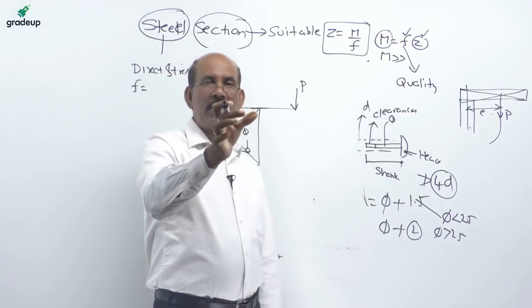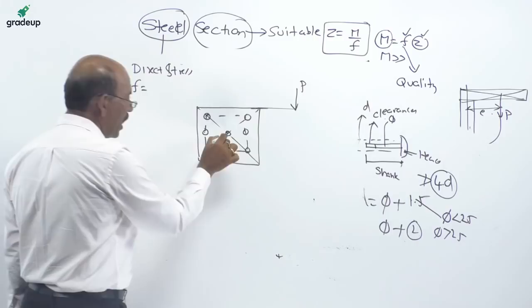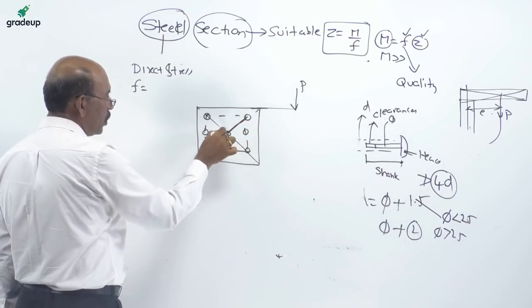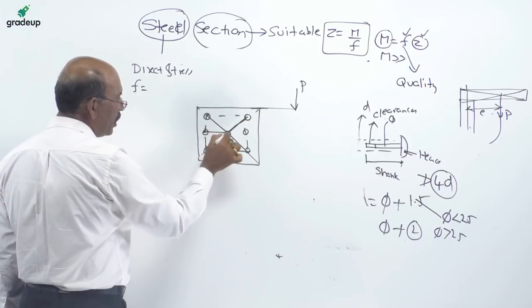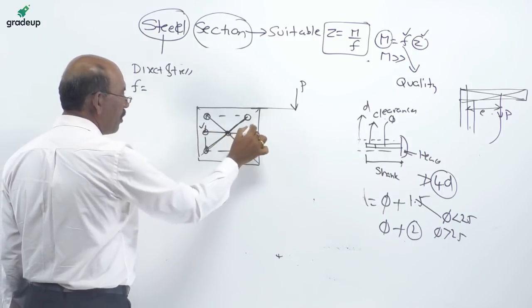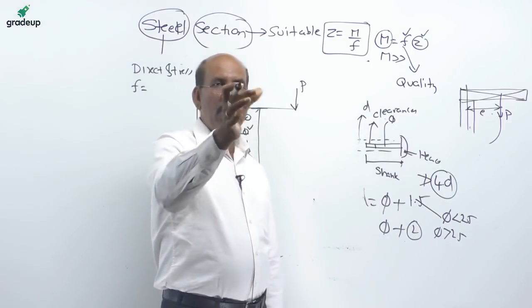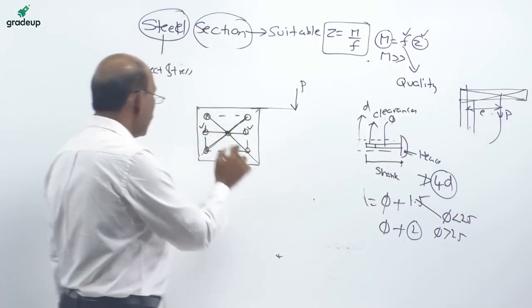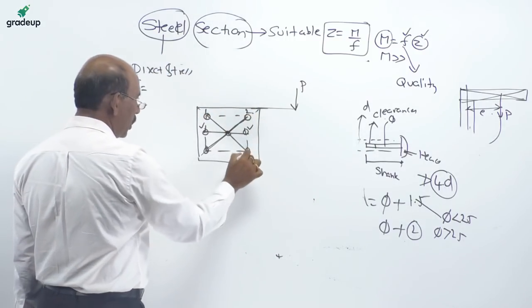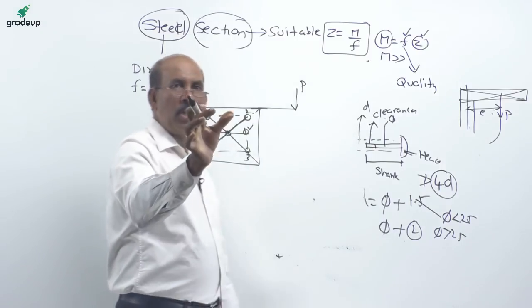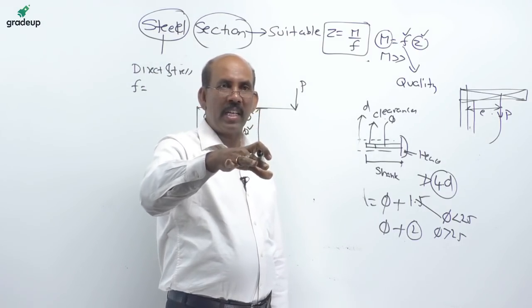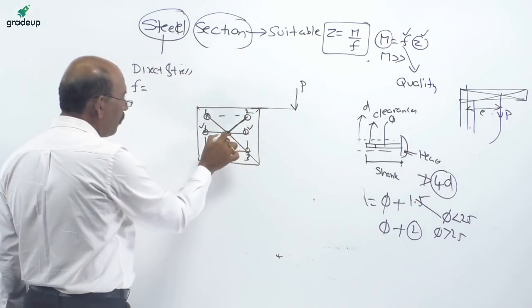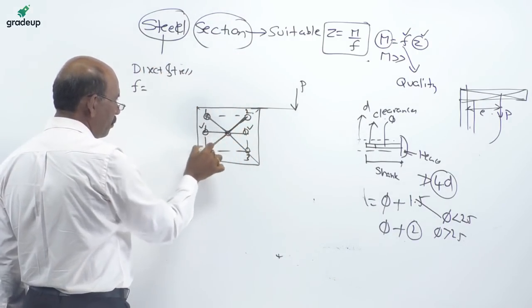So, the bending stress depends upon this radial distance. For example, if you see, this value is less for these two bolts, which means they are not critical. Only these bolts 1, 2, 3, 4 are very critical, because they are all at the same radial distance.